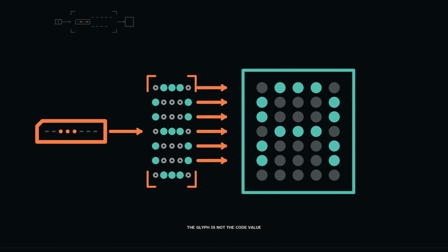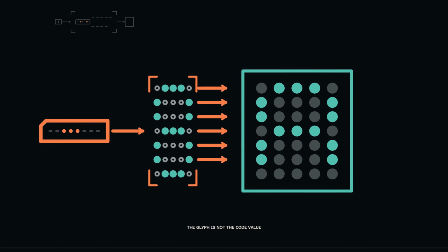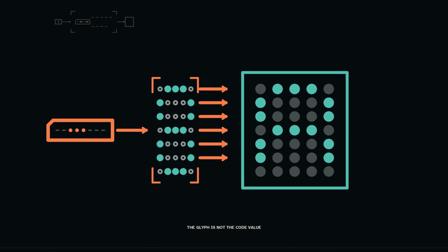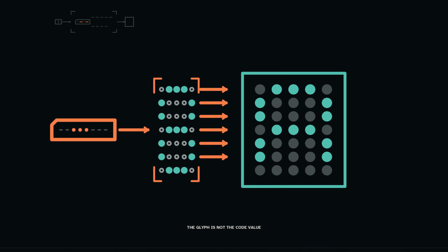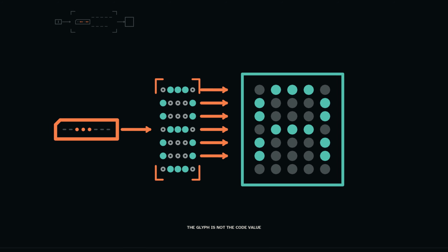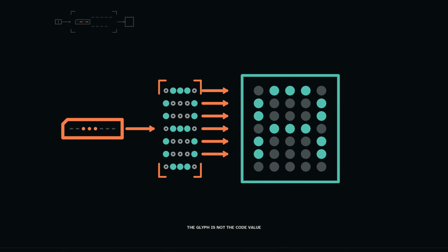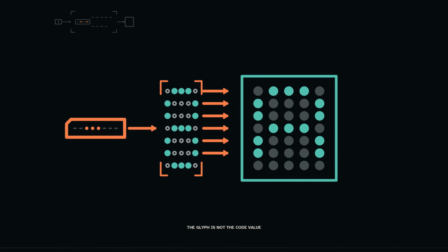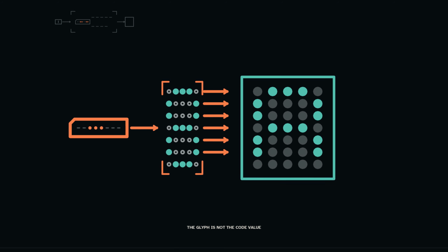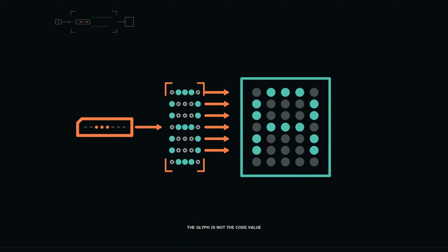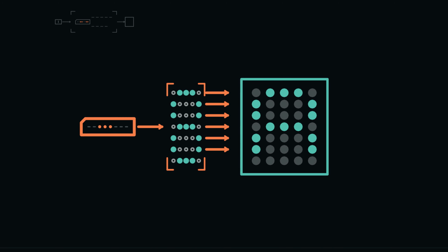Read the finished image backward. A foreground pixel is active because its row mask contains 1 at that column. That row mask came from the font entry selected for the code hexadecimal 38. The code reached the display register because the processor stored it there. If a single row bit were changed from 1 to 0, which pixel would change? If the code changed to hexadecimal 37, which mechanism would select different row data? Reverse tracing makes every visible mark answerable.